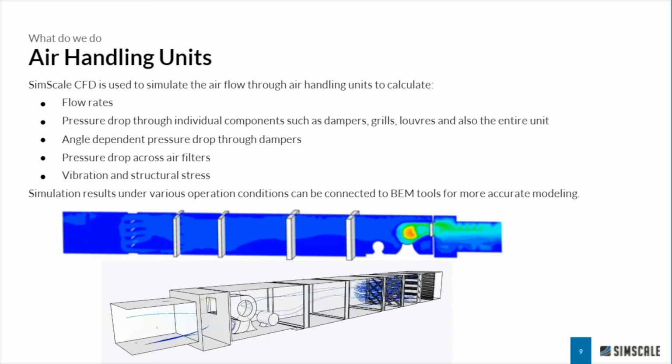What usually is done is, if you're not really sure if a specific component will be sufficient or not for your situation, it is oversized, right? So fans, the blowers are oversized, the heating and cooling elements are oversized, so we can be sure that they can actually get the required performance in the actual operations.